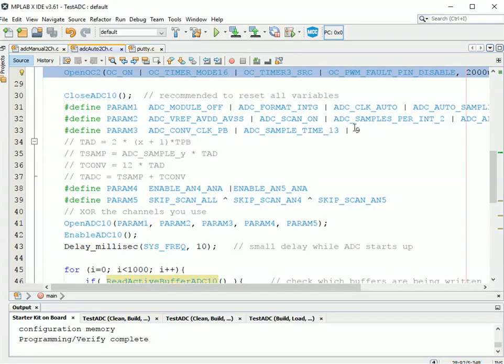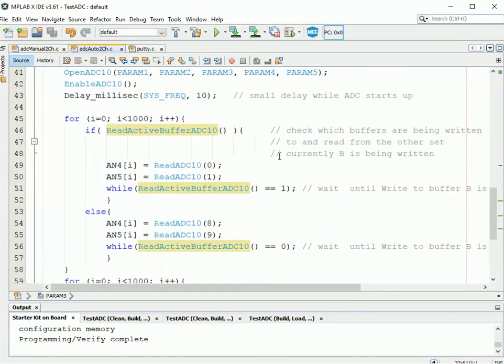I've chosen a certain sample time and value of x to calculate to determine what my sampling time is. And down here, I have a for loop to collect 1,000 measurements. Actually, 1,000 measurements times 2, because it's 2 channels I'm using. So 2,000 measurements. It's running before I do this sample. It's running after I do this sample. Okay, so that's just sampling from the continuous ADC.